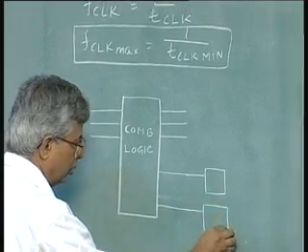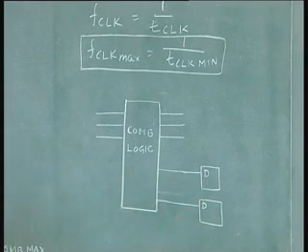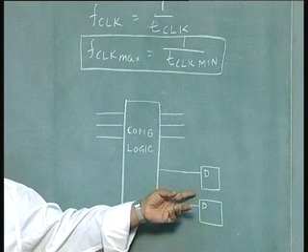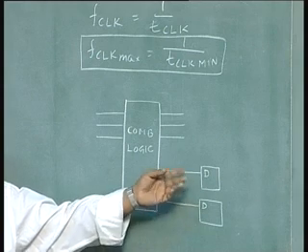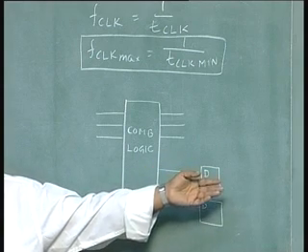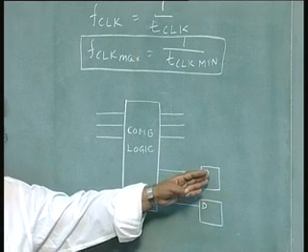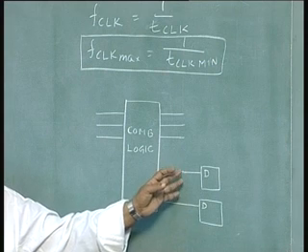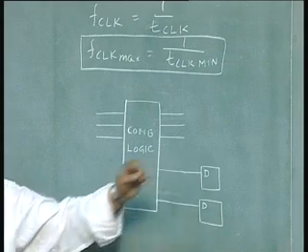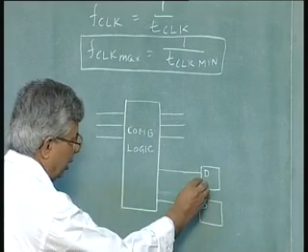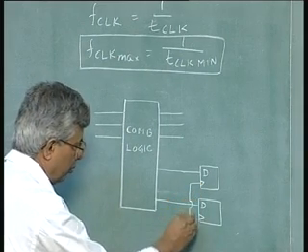and they need clocks. In a simple model we will use a D flip flop here, though it can be any type of flip flop, for example a JK flip flop. In that case we need a J input and a K input to get the next output. In this case we have a D, and the advantage of a D flip flop is that the input is the same as the output after the clock period. So, whatever you want to store will be directly put here. In the case of JK, in order to store something we need to find the input combination of J and K which generates the data 1 or 0 to be stored. So, let us make this simpler by using D flip flops, which are clocked, and we can have a single clock to clock both of them.